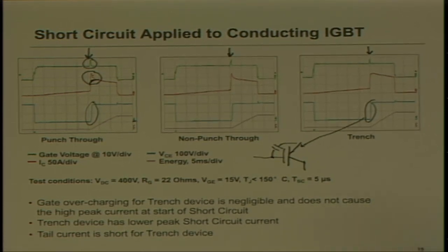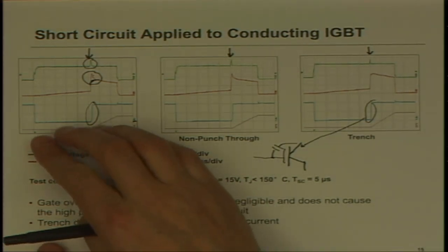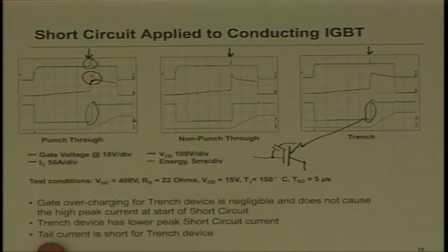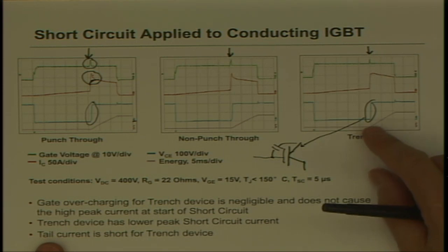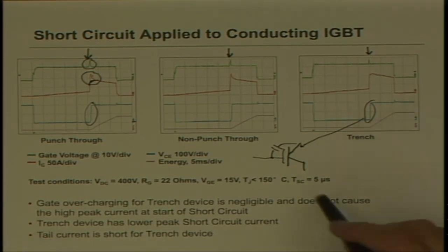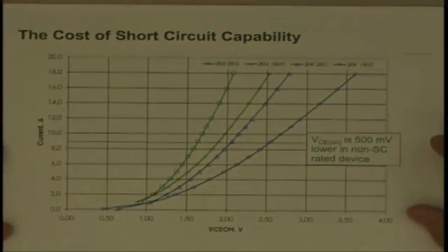And the other thing is, in the olden days, 10 microseconds was barely enough time to detect a short circuit and be able to do something about it. Now, usually short circuit detection is more like in the 2 to 5 microsecond range more commonly, because faster ICs were able to detect and react more quickly.